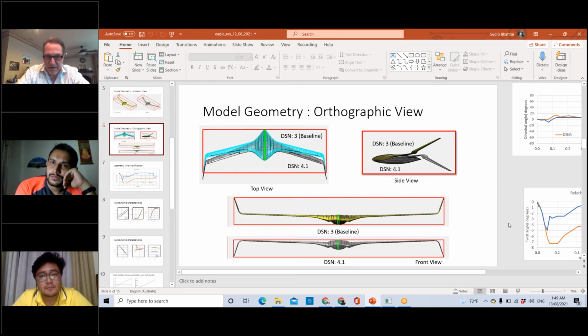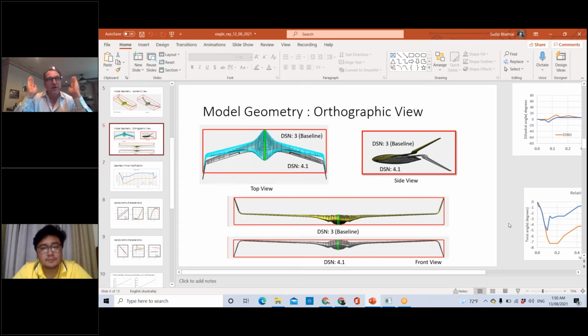Yes. So if that's an option you could exercise, you might want to take a look at doing that maybe at 2 or 3 different incidences, because as I go forward, yes, it will pick up more lift. So the winglets are working harder. And if it's reducing vortex drag, that means the winglets want to work harder. That's good. The question would be, if I had them aft, I'm not saying that we want them that far aft, but if I had them that far aft and I put more bite into them so they would toe in to load, that's another way I could load it up.